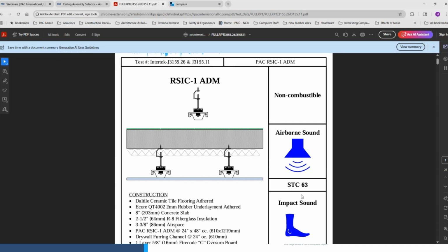So you're going to get sound transmission through your test specimen, but you're also going to get sound transmission through the floor and ceiling that's all the way around them. So ideally, the lab is designed so that you get very little sound transmission through the rest of the lab, and all the sound that you're measuring in the space below is through just the thing that you're testing.